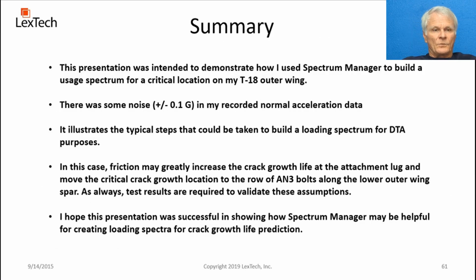Finally, I just wanted to say that this presentation was intended to demonstrate how I use Spectrum Manager to build a spectrum. You'll be different. Every location's different. I just wanted to go through the process. I also want to point out that there was some noise, approximately plus or minus 0.1 G in the recorded data. So there's always going to be some error there.